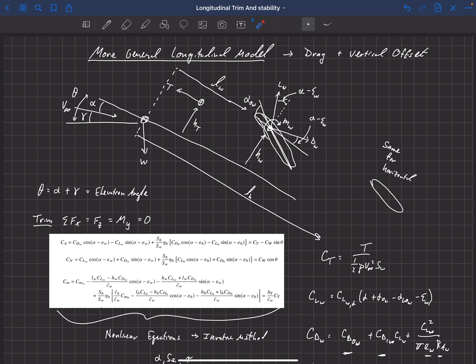And another dangerous scenario is actually on landing. When we come in, if for some reason the pilot has to do a go around, because on landing we have very little thrust up here, and maybe we have our thrust at idle, or even to a point where there's drag up here. So we're trimmed as we come into land, and our horizontal is offsetting that in order to trim the aircraft.